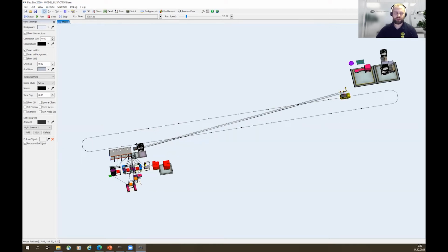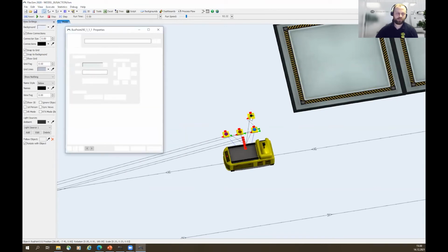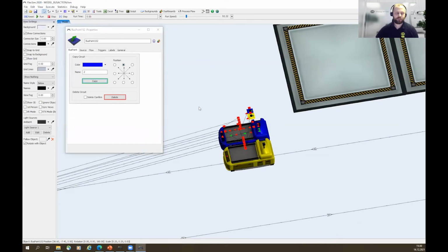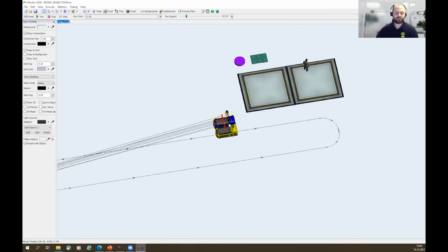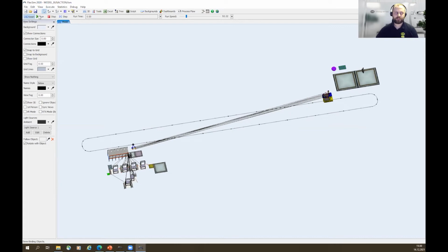Then, of course, our line is not supplied well and we need to fix it. The easiest thing I can do in here is to simply open the bus point and copy the whole circuit, which means it creates the same logic for the second Tiger train, or AGV in this case, with everything already set in the same manner.